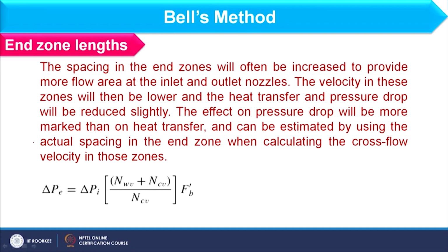Okay. So, here is another point you should consider: in the end zone the spacing is different than what we considered in the cross flow zone between two baffles. So, in this case we should consider pressure drop in a slightly different manner.